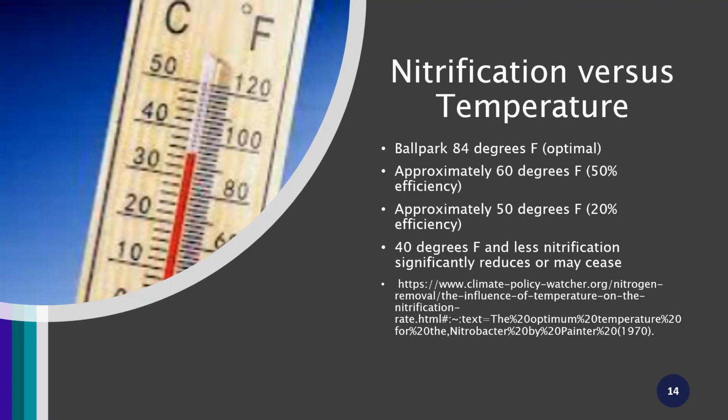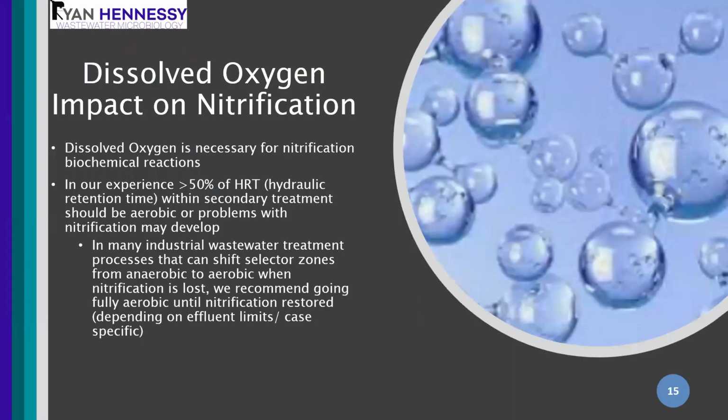So once you get below about 40 degrees Fahrenheit, it's very difficult to nitrify. But as it gets warmer, it's certainly easier.